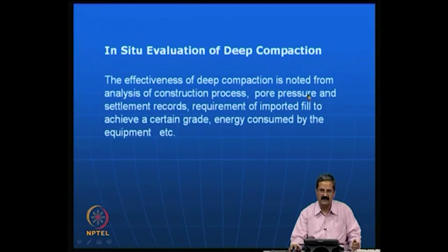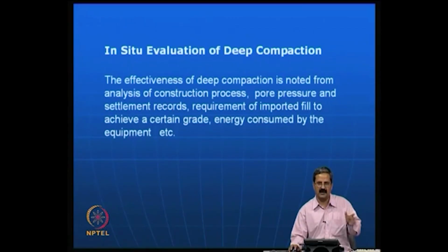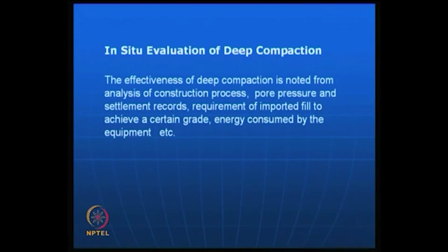In clays, for example, pore pressure mobilization is very important. So, you need to decide the time lag for the next tamping. You have done a few tampings now, so when do you release the weight the next time? You can get an idea from the pore pressure and settlement observations so that things are effective.